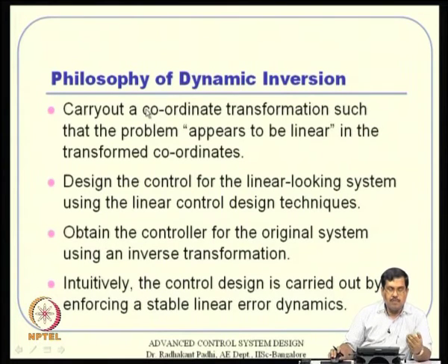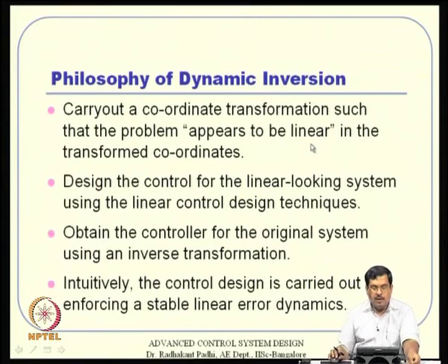We want to talk about some sort of a design approach for nonlinear systems directly, and the philosophy of dynamic inversion is something like this. We first carry out a coordinate transformation such that the problem appears to be linear in the transformed coordinates. It is really not a linear problem. We are not linearizing the problem at all, but in the transformed coordinate system, the problem appears to be linear.